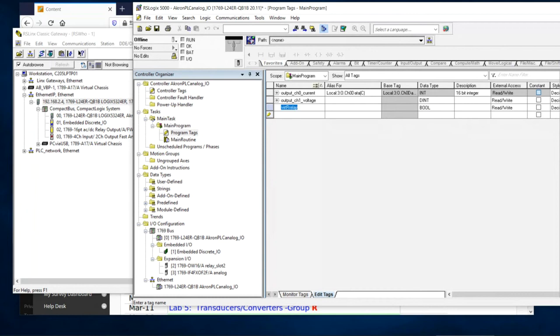So this virtual relay is 1 bit, so it's a Boolean, but if it's virtual, it means it's just being stored within the memory inside of the PLC, and it has no real-world physical connection or interaction. And so therefore, we just put in here virtual relay. Under the alias, nothing goes because it's not a physical wiring.